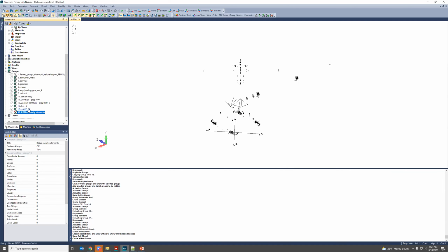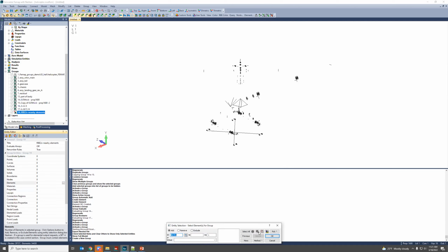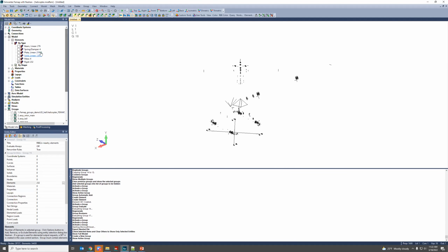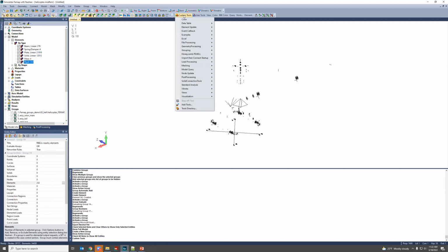All right, so here we are with this group. I want to put all of the IDs of these rigids in there. So I'm going to click this button with the three little dots. That will bring me to element ID, and I'll just box select all of those. I'm going to switch back to viewing active group, but I'm also going to be sure to turn the rest of my elements back on, so that you can see when I run this API, which will be under custom tools for your version of Femap. And these are all the APIs that just ship with Femap.